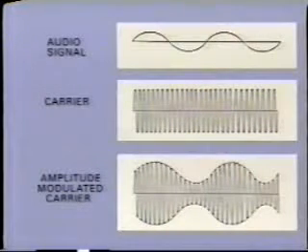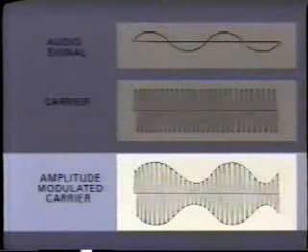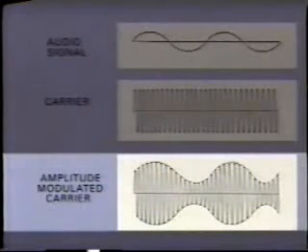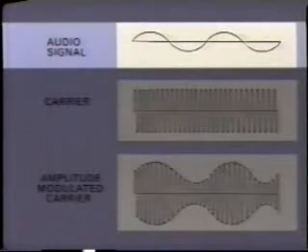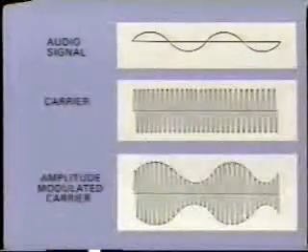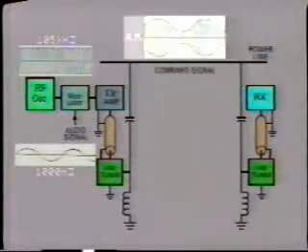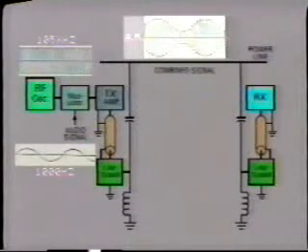Let's take a closer look at these waveforms. The modulated signal looks like this. You can see that when the carrier signal is removed by demodulation at the receiving end, only the audio wave remains, so the speech pattern can be recognized. Note that the amplitude modulation affects both sides of the wave and produces an envelope. When this signal is demodulated and analyzed, there are actually 3 frequencies present at any instant.